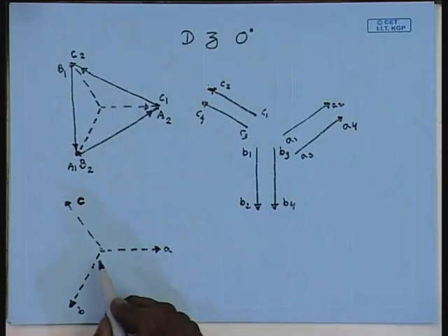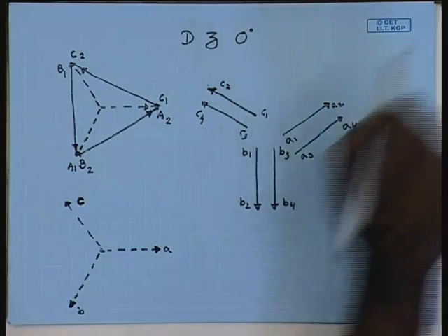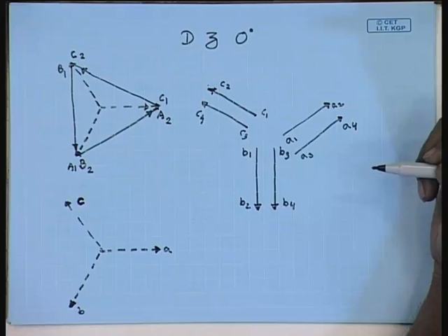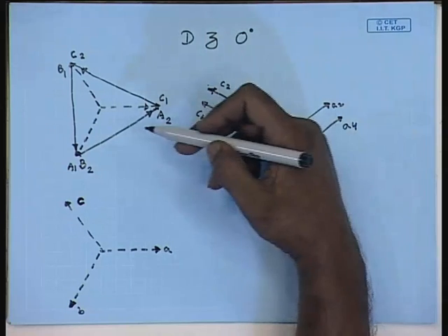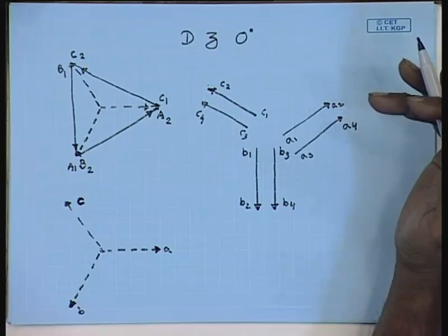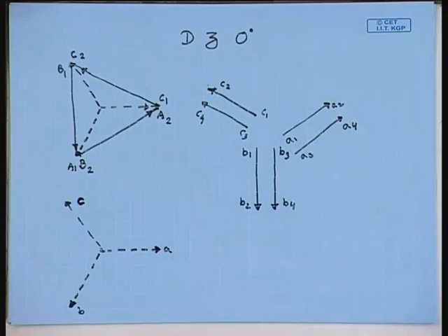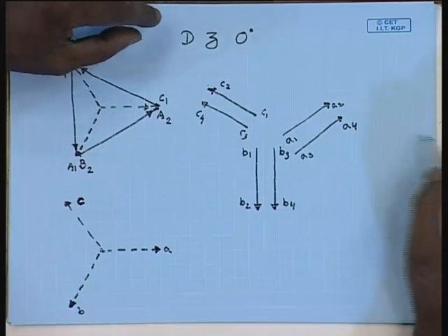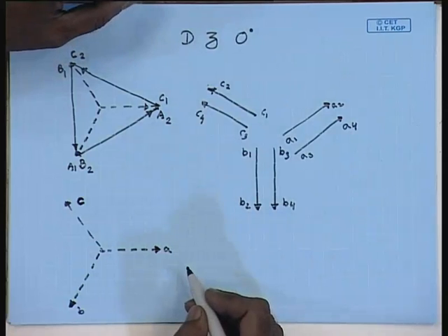So, how can I construct this line to neutral voltage phasor of a zigzag winding using two different phase voltages? One of them will belong to the A phase, the other should be either B phase or C phase. It is usually the last one that will be the A phase.